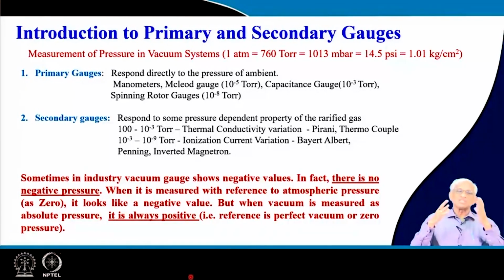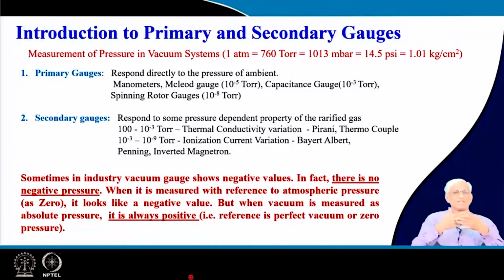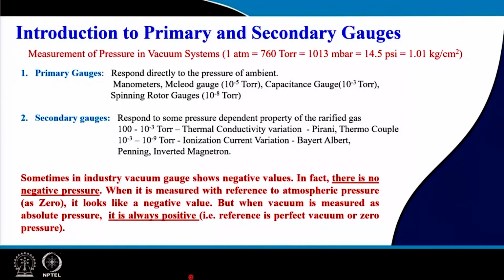The engineers working in that refrigeration industry are more bothered about their lifeline: refrigeration, high pressure, filling, freon. They are not worried about a few minutes of evacuating. So, for them it is a small aspect of it. They will say minus, and they get mentally convinced that now I am removing the gas, so pressure is going negative. This is why I am saying, I found this problem.